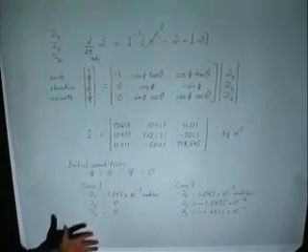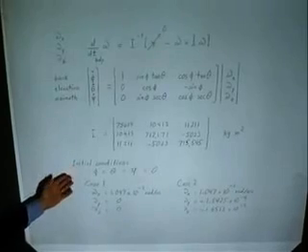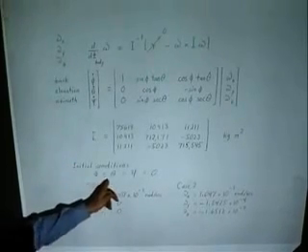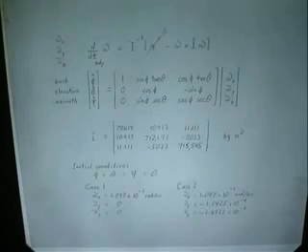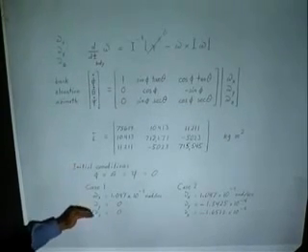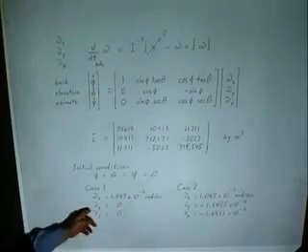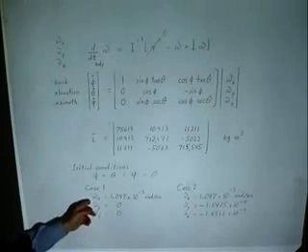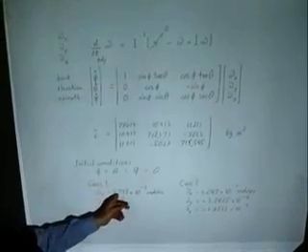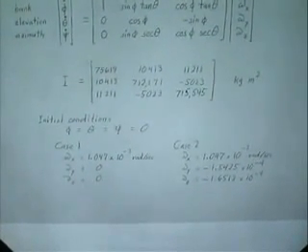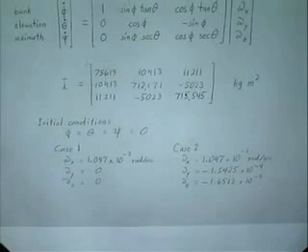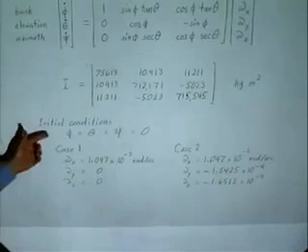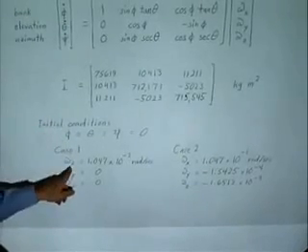And so in the first case that we simulated, the initial conditions were set: all the Euler angles to 0, 0 roll, pitch, and yaw angles, and start with 0 pitch rate, yaw rate, and a very, very small roll rate equal to 1 revolution per, we used, 10 minutes. Joe later used 20 minutes in the simulation he did 40 years ago. But for the purpose of this lecture, we did 1 revolution per 10 minutes.